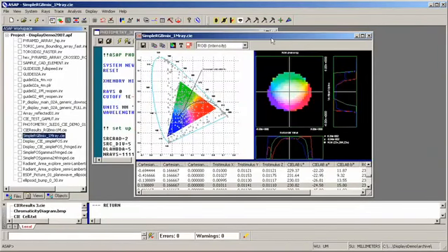Finally, at even higher resolution, I have the 1 million rays, and we really start to get an idea for what a completely smooth result would be. It takes many more rays to do this at a resolution that eliminates the jagged edges, but that's just a matter of time, and in this case, it's an example that runs in just a few minutes. Typically, if you were doing this as a quantitative job for a real display design, you might sample many points on the display, and each of them might take a few hours. But in the overall program of analyzing a display, that's still a fairly small investment in time.